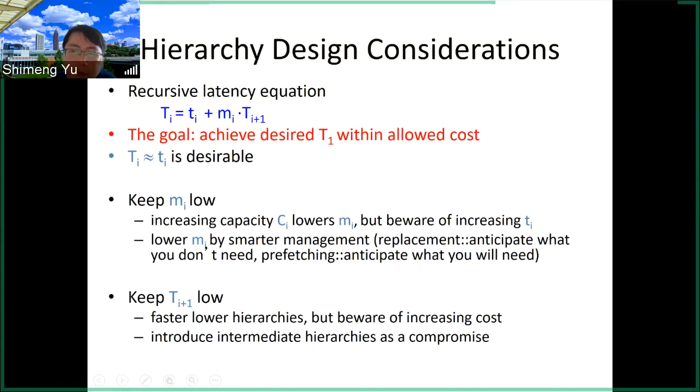This is simply because if you think about the memory array size, we have the rows and columns, right? Now you increase the capacity, it's like you increase the size of the memory. You have more rows and more columns, so the wire distance is going to be longer. So when you access the data, you need to have the input like the row address, and then you apply the voltage here, and this voltage will need to propagate along the wire to this location, and then you get the data.